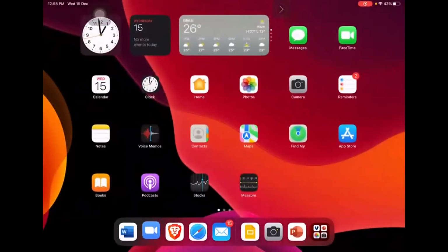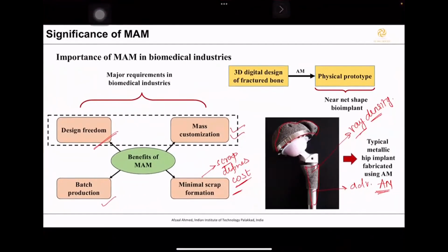Please go ahead. In the finishing processes, that is, the post-processing, let it be laser, abrasive polishing, mechanical, or even wire electrical discharge polishing, it is basically focusing on the external surfaces of the additive manufactured part. So if I have a complex internal geometry in a part, is there any specific method in post-processing that can improve the surface properties?